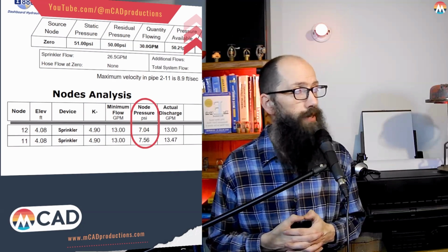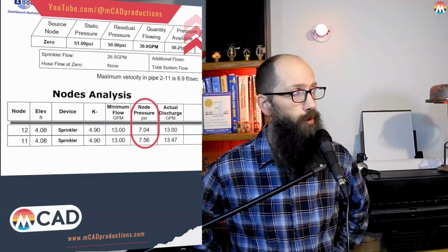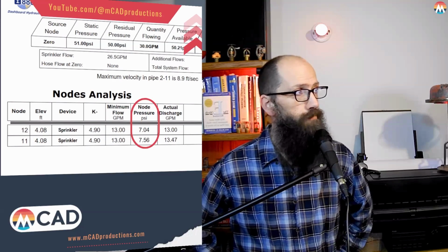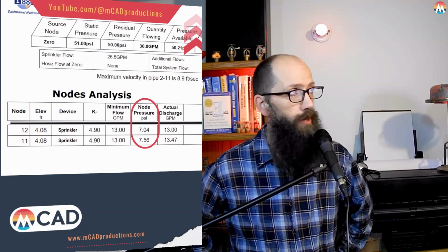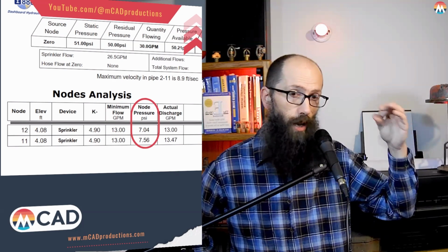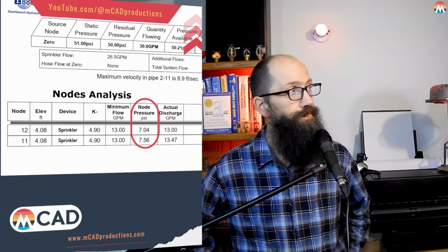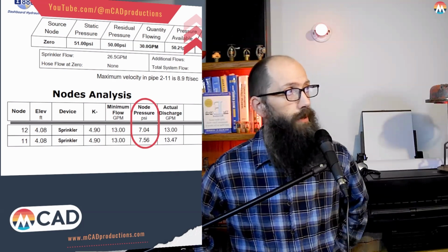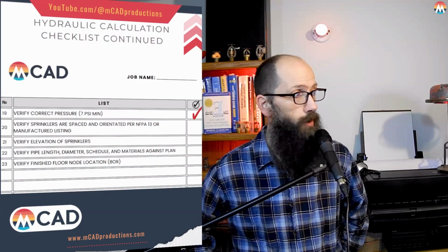That's why on this sprinkler, it doesn't go below 13 when you go down to the 12 by 12 and the 14 by 14. But they can achieve that on the other sprinkler. I think it was a 3 point something, because they can operate the head with lower pressure by making a smaller hole. When you're lowering the K factor, you're lowering the size of the hole that the water's coming through.